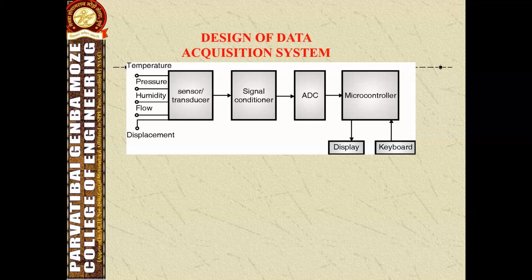The objectives of the data acquisition systems are: first, it must acquire essential data at the correct speed and correct time. Second, the data acquired must be efficiently used so that operators know the state of the system. In order to maintain online, optimum and safe operation, the system must be continuously monitored. Then, the data acquisition system must be able to collect, summarize and store data for diagnosis of the operation and for record purposes. An effective human interface needs to be provided by the data acquisition system.